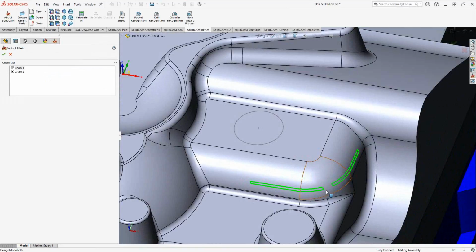So this is a way to limit the travel of the tool on a particular surface, but only for a certain surface angle. And the purpose of something like this would be to limit the travel of the tool so that you're not wasting time calculating for the entire part just to find out that those are the particular areas that would meet that angle limit. So this is one of the truer versions of the constraint boundaries where you're looking for something very specific on your model and you're allowing the software to calculate where that specific area would be so that you can generate whatever tool paths you're looking for.